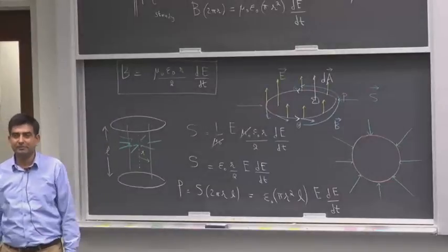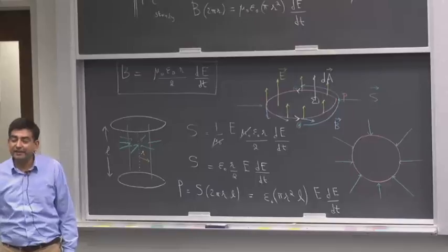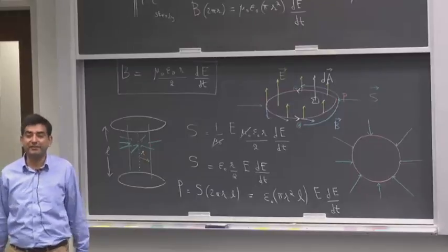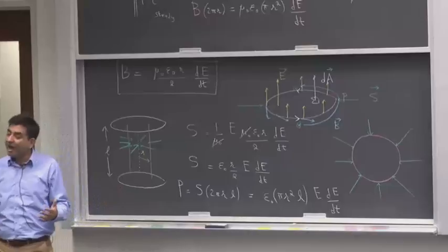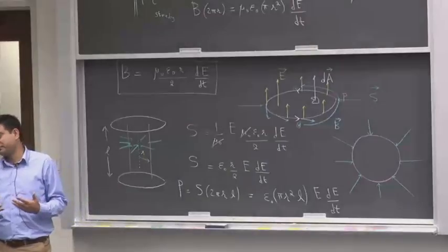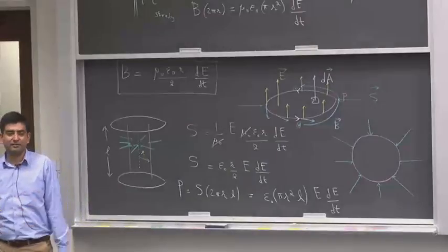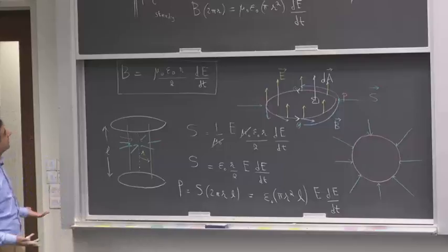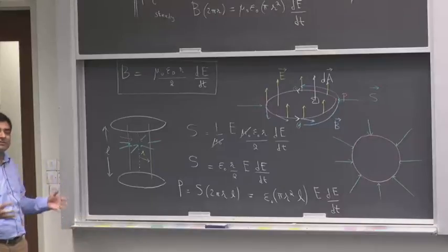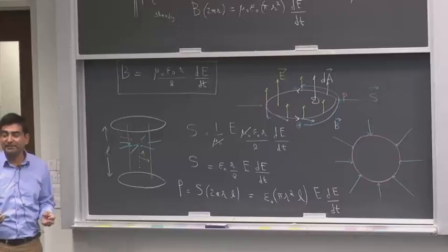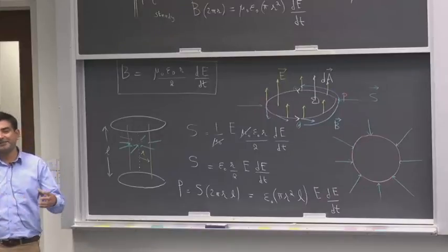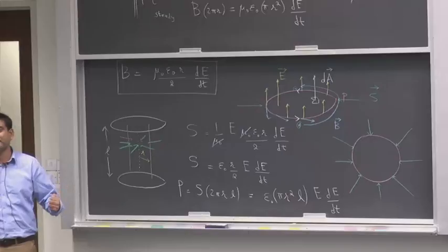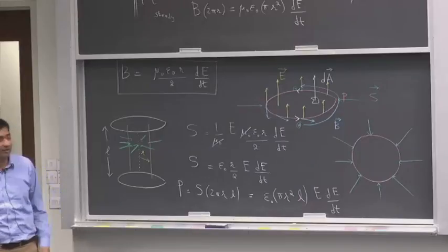It is going into the form of electric fields. The electric field is building up. That electric field harbors energy. It has energy in it. There's no motion taking place, there's no heating up that's taking place. So the energy is just dumping into the electric field, which means that this capacitor is acting like a spring that is extending with time. It stores elastic energy, it stores electric energy in this case.